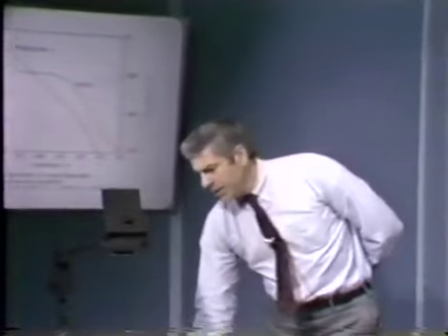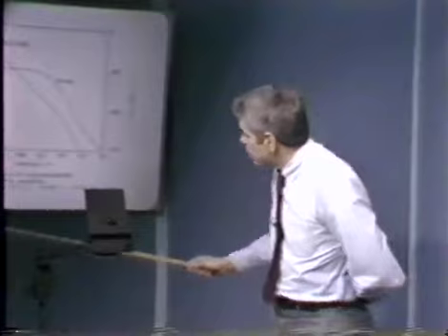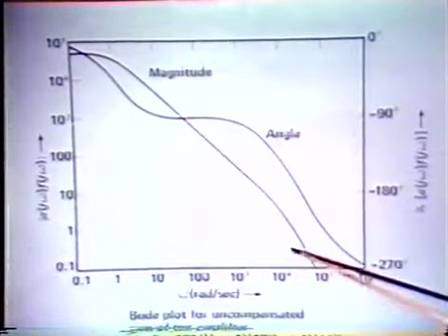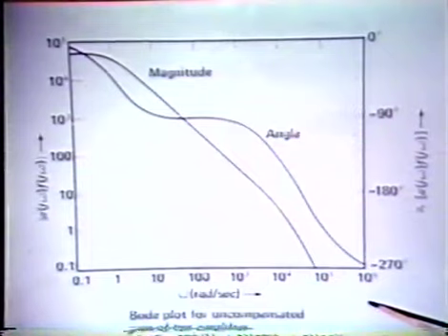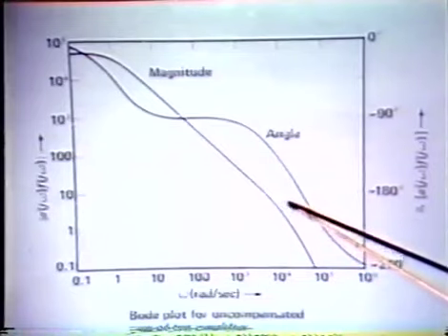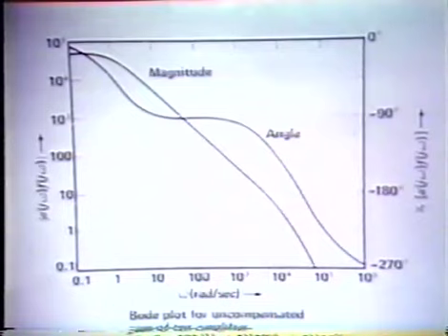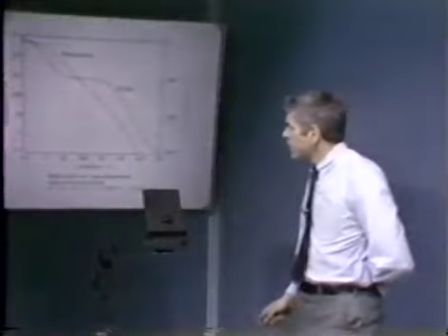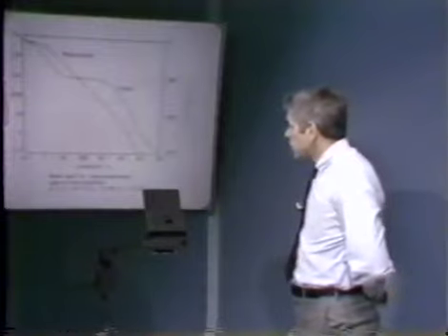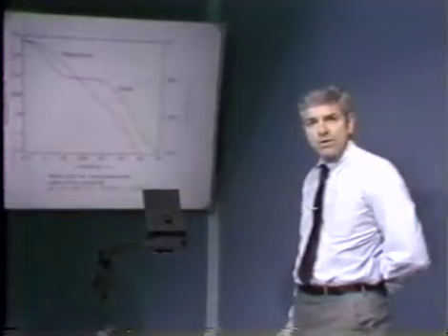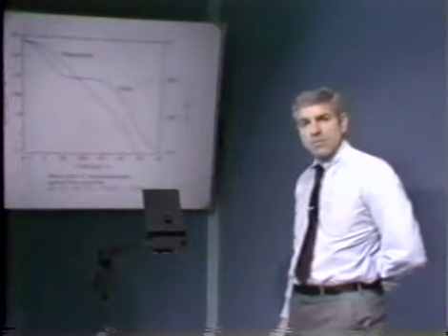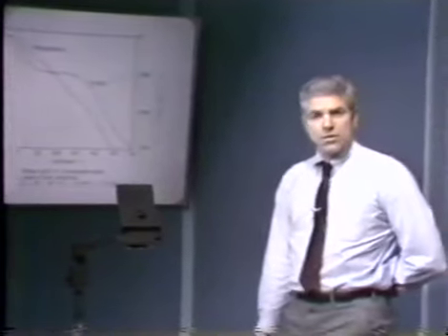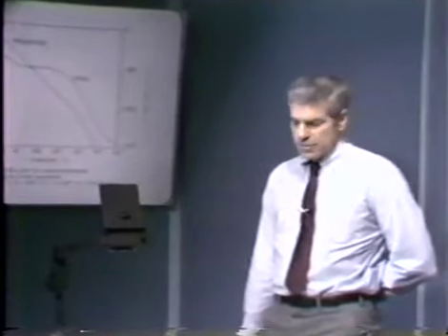And if we do that, we find out that a good location for the zero is somewhere on the order of 2.5 times 10 to the 4th radians per second. If we added a zero somewhere in here, and of course we get a pole because of the characteristics of the feedback network, a factor of 10 above that, we end up with about the maximum positive phase shift we're able to achieve, and consequently we end up with maximum phase margin for our system. So here we've lived within the constraints. We can build a lead network with an alpha of 10, since that was the attenuation associated with the feedback network. We're able to use that as the maximum spread between the pole and zero in our lead network. And we live within that constraint, and we choose the best location for the zero in terms of improving the phase margin of the system.